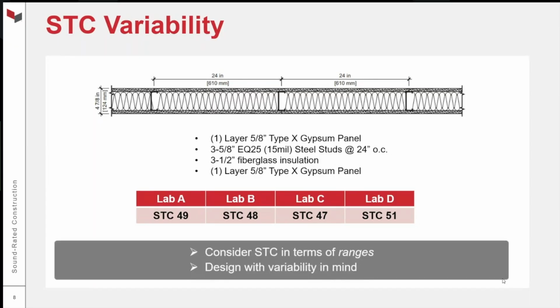When I talk to contractors and designers, I really encourage everyone to think about STC in terms of ranges, and to think about this variability when you're doing your design work. If you're a contractor, you inherit a partition schedule and you're trying to make sense of those ratings. Plus or minus 1 STC point, plus or minus 2 STC points is not considered a significant difference if it's within that laboratory variability. So it's a good thing to keep in mind.